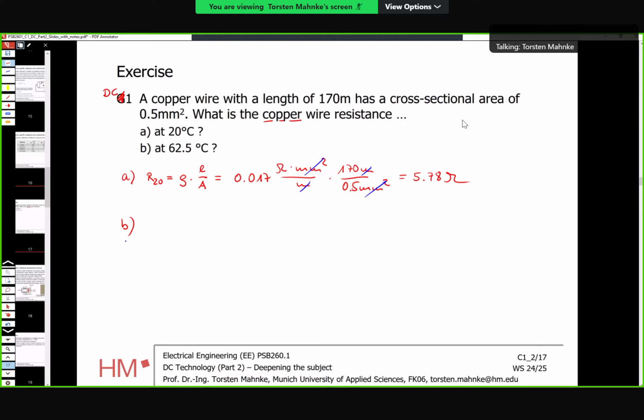You don't have to. If you write down the right units in this solution and just write down this as it is given in square millimeters, then you can just eliminate the square millimeters. You don't need to convert it into meters. This way, you made a mistake. It's a factor of 1,000, something like that. No, it's 1,000 to the power of 2. Okay, so keep in mind, always write down values and units and work with the units.